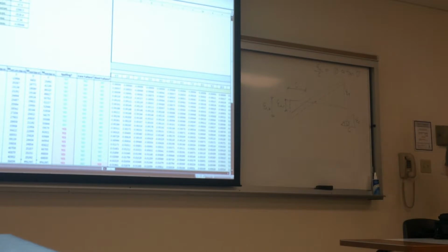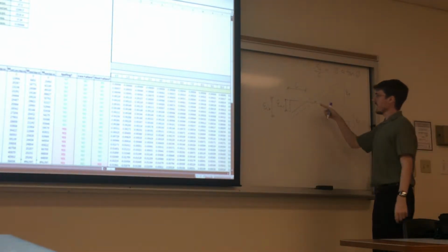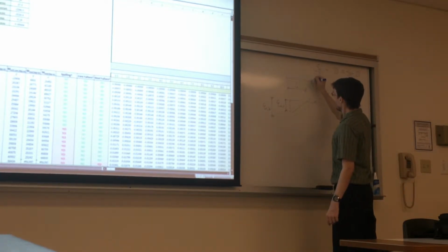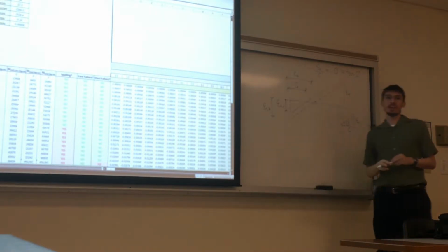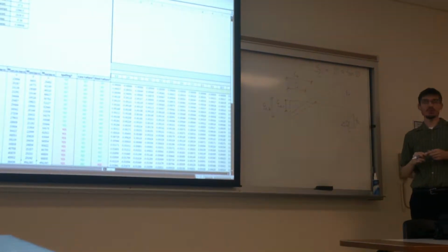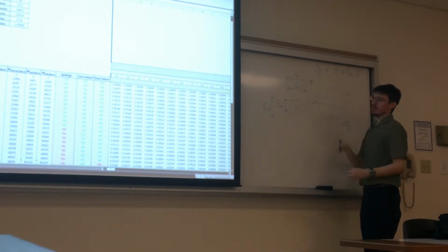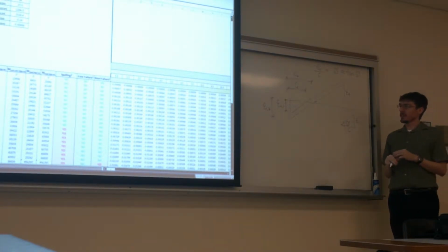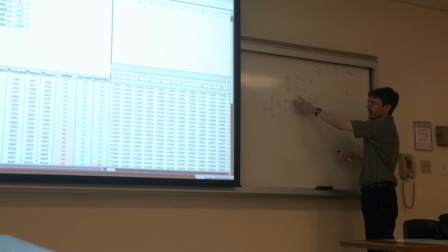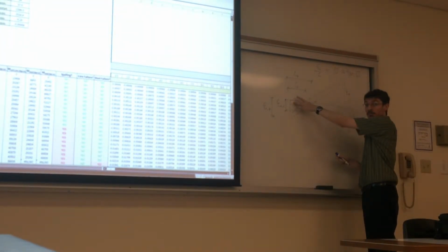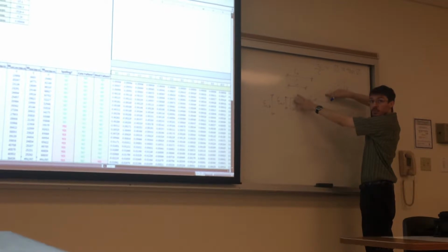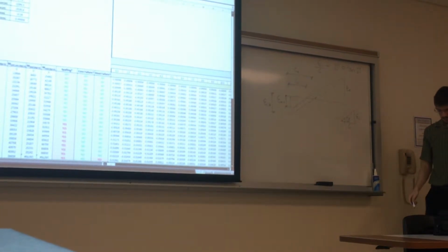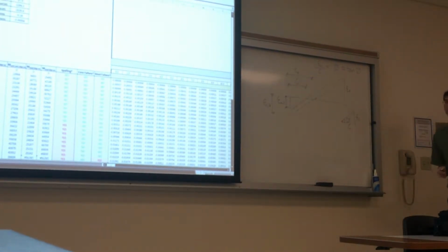You have, let's say, your different guesses, epsilon c1 and epsilon c2. And what would happen then is you'd get a c1 and a c2, because you're changing how much compressive strain is in the section as a whole. You're moving this profile up and down as you're iterating. So you're telling Excel, basically, find me the balance point where the amount of compression generated from the strain profile is equal to the amount of tension generated by the strain profile on either side. Does that make more sense?